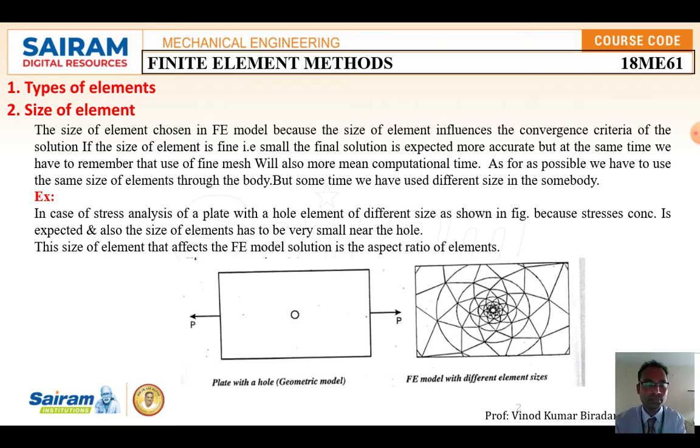Look at this diagram. Let us assume a plate with a hole. This is a geometrical model. We want to calculate where the maximum stress is and where the minimum stress is in the analysis part. What is the first step? To divide it into small pieces.